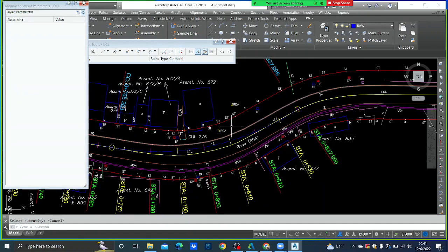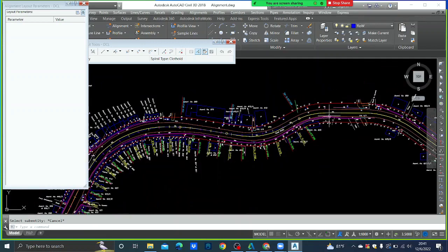That is all you can do, because lesser than 95, of course you can't go, because it is not according to our standard. But you know, in extreme situations, maybe you can go one step down in design speeds. That means instead of 50 kmph, you can select 40 kmph. Understood?